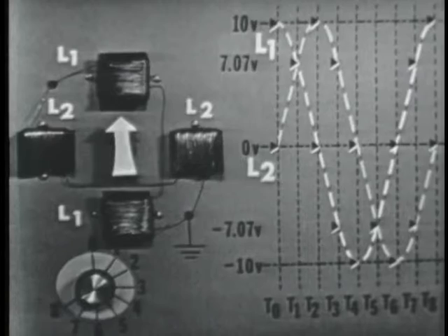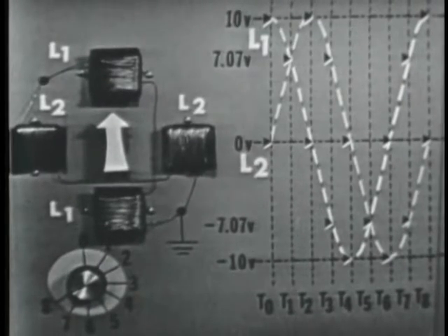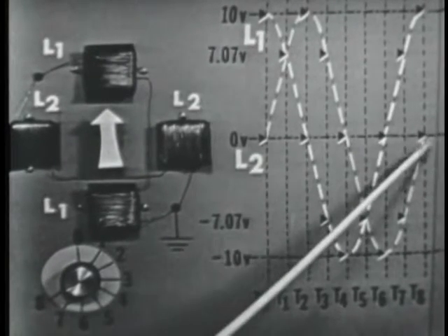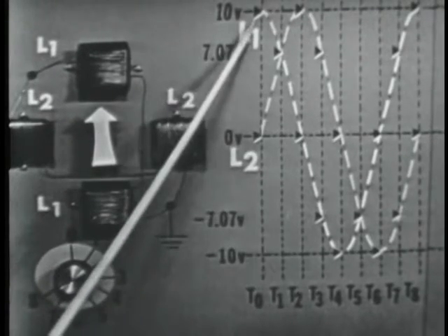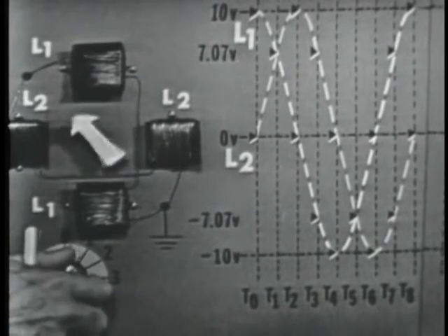we're back at 0 degrees, where we started. And our voltages and polarities are also at the same values we started with. L2 is at 0 volts, L1 is at max positive. So we have rotated the magnetic field 360 degrees.